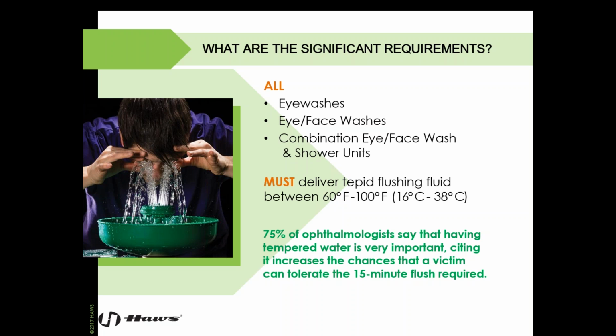We have talked with some plant managers where this has been an issue because you have the victim who goes into the shower, and if they cannot stay in there for the full 15 minutes, one, they're in more jeopardy, or two, you endanger others because they're having to hold them in for the full 15 minutes, and then they can be contaminated as well.